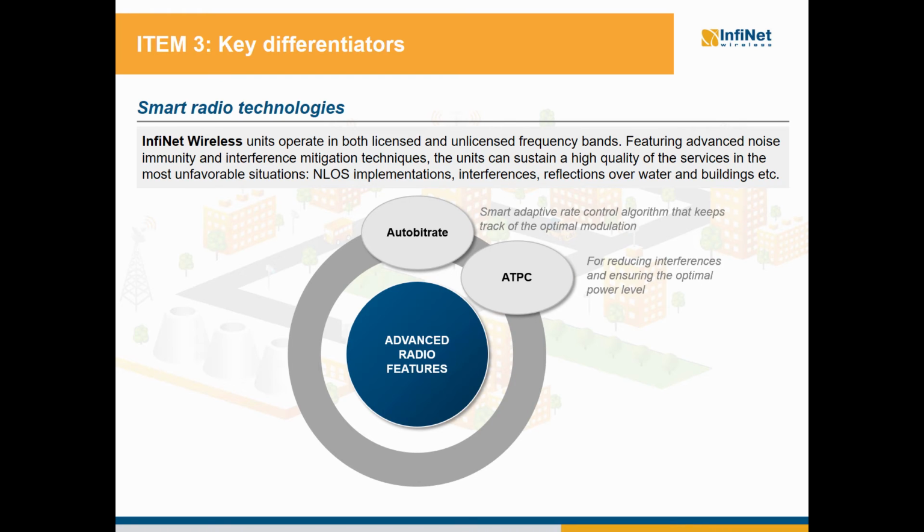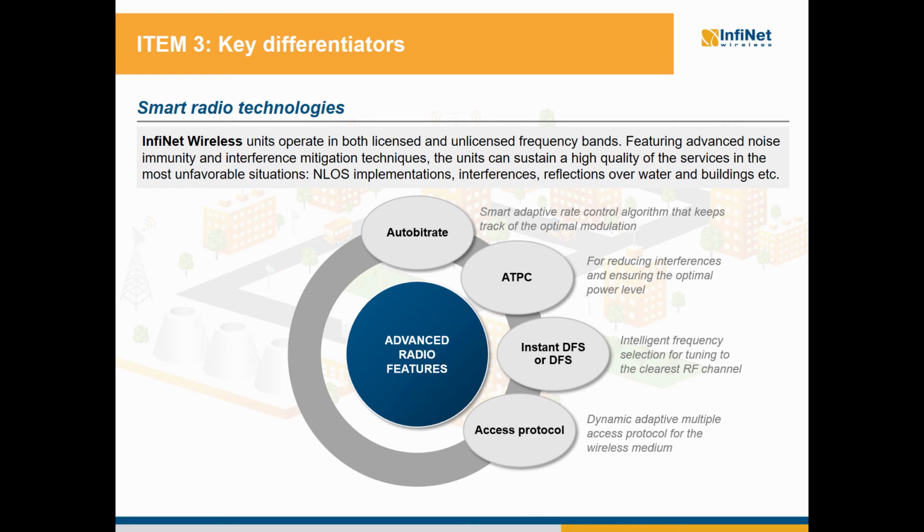ATPC is also available for reducing interferences and ensuring the optimal power level. DFS and instant DFS ensure an intelligent frequency selection by tuning to the clearest RF channel. We have dynamic adaptive multiple access protocol for the wireless medium. Tools that help you with an in-depth radio channel diagnostic are also available, like spectrum analyzer, radio sources, and antenna